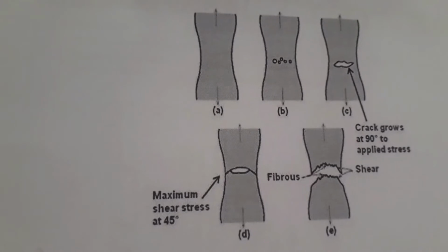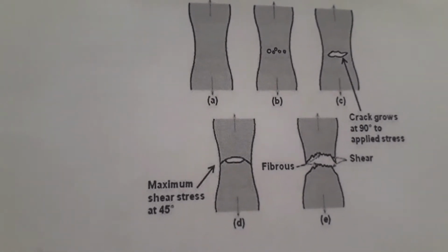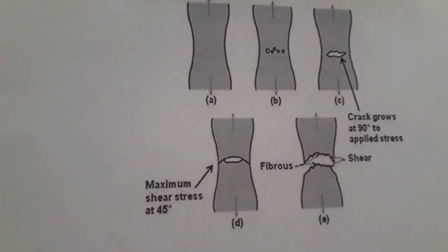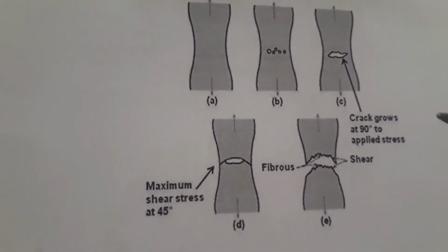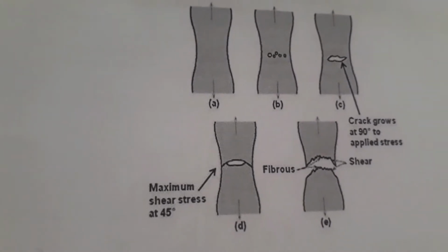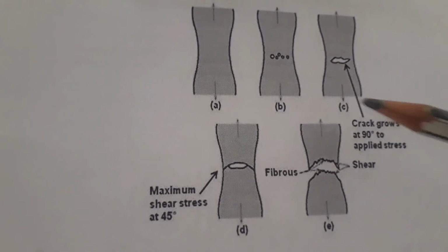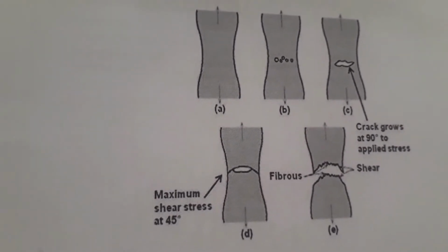So normally, what are the stages of the ductile fracture? See, these are the ductile fracture stages. The failure of the ductile material under tensile loading can be attributed to cup and cone fracture. See, cup and cone fractures. This form of ductile fracture occurs in stages after necking. First, small micro voids form in the interior of the material.